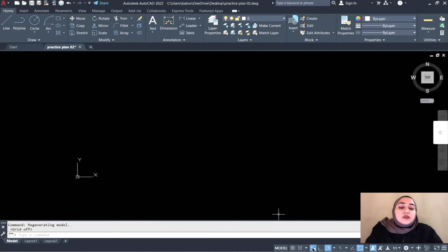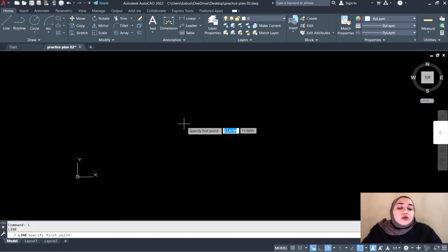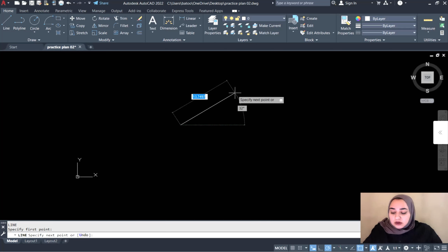Then I'm going to make sure that my dynamic input or dynamic mode is on. And this basically helps me whenever I start any line or any other command, it will show me this down menu in here. Also when I'm writing, it's going to show the dimensions on my model space, instead of, for example, only showing them down here. So I can see everything in here on my screen. It is very clear. This is because of dynamic input.